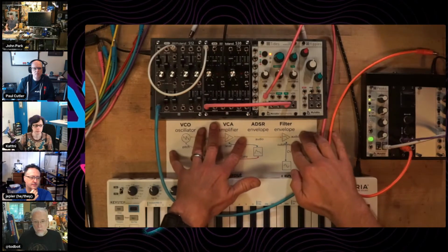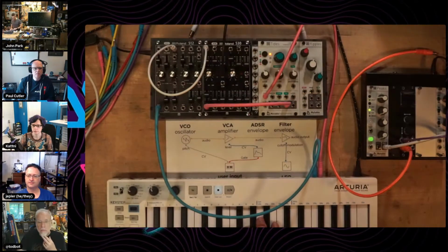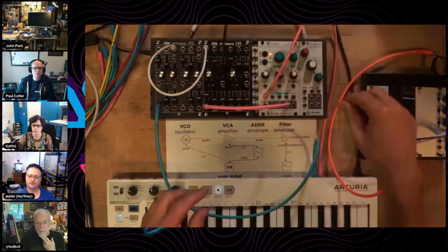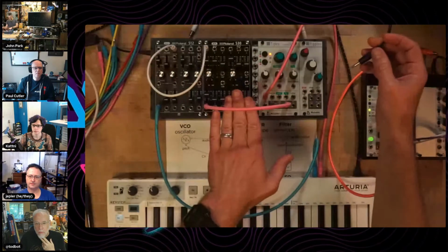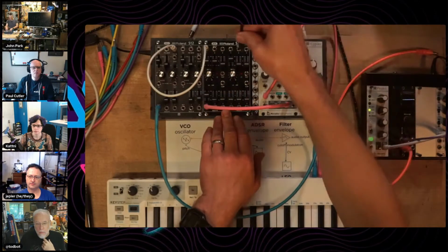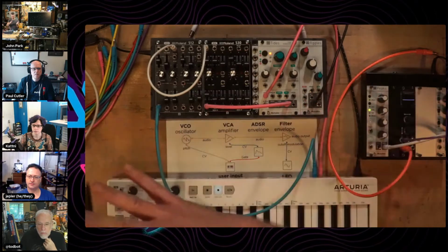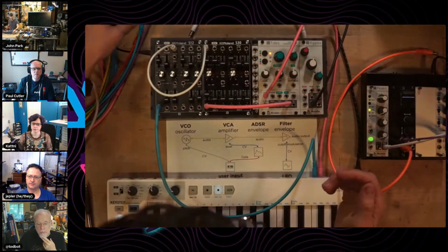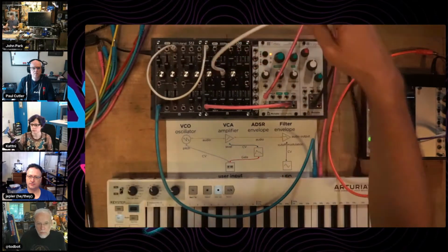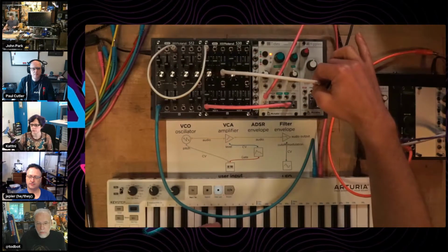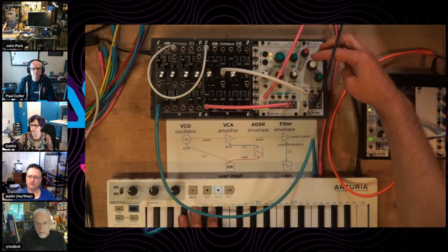We then are just putting icing on the cake here with a thing called a filter. So this is a way to shape some of that harmonic content. So what I'll do is send my output from the amplification, rather than straight out to my speaker. I'm going to send it through a thing that's going to filter that. So we can filter frequencies with it. We can also emphasize certain frequencies with it. Let's take the output from the VCA, which is being shaped by the envelope, and put that into the input of a filter. And I'm just going to hold a note here and play around with that filter frequency.